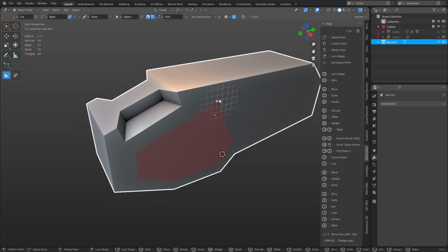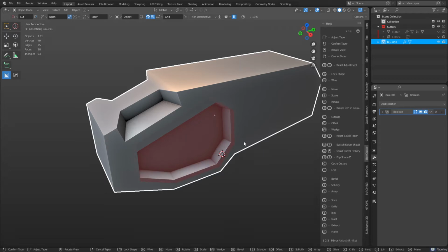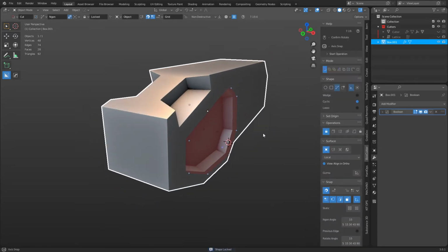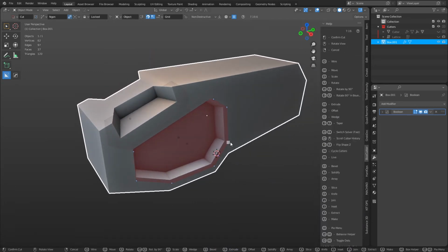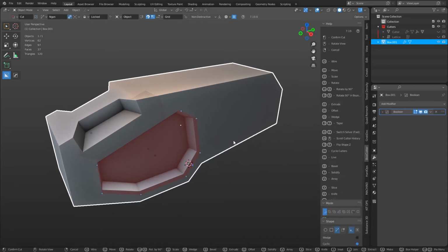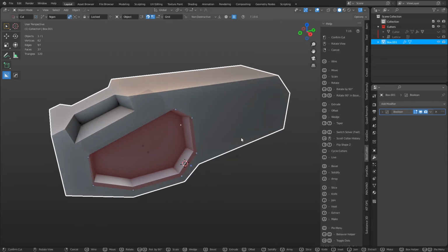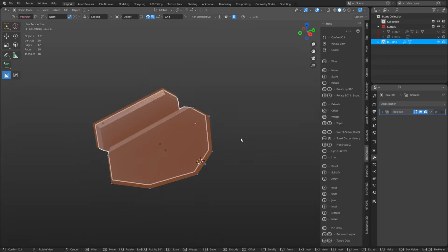So we could do a cut like this, perhaps. Cut inwards, hit E, there we go. We could do Shift T, do a taper. Okay. I'm not mirroring it right now, but I could by pressing 3. You can see how many little shortcuts you have here to use. So you can toggle through cutters or the cut modes by pressing X. Always try that as well.